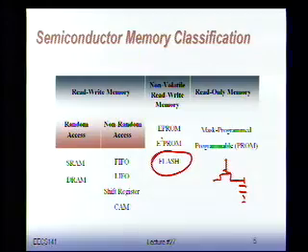So you can actually program an open circuit or a closed circuit by moving the threshold of your transistors around. And that's really what most flash memories do. It's a transistor using programmable thresholds. And the programming of thresholds is done by a bunch of tricks, but it's mostly by trapping charge onto an oxide. Okay? So that's one way.